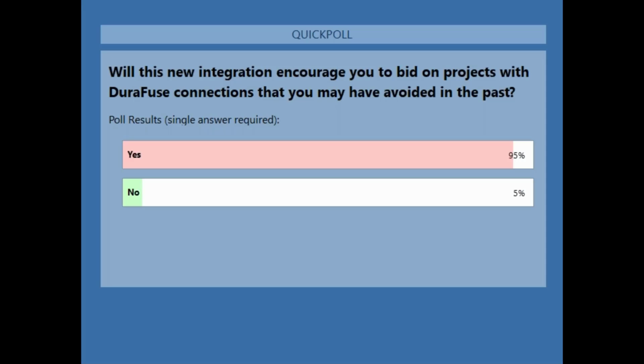Next question, is the connection still possible when the beam flange width is wider than the column flange width? Yeah, that's one of the really cool things about this connection, there's a lot more flexibility in beam and column combinations. I don't think it's beyond the capability of the current plugin, but we do have details that handle that, and that shows up in unique cases. But we can handle beams that are wider than the column flange width.